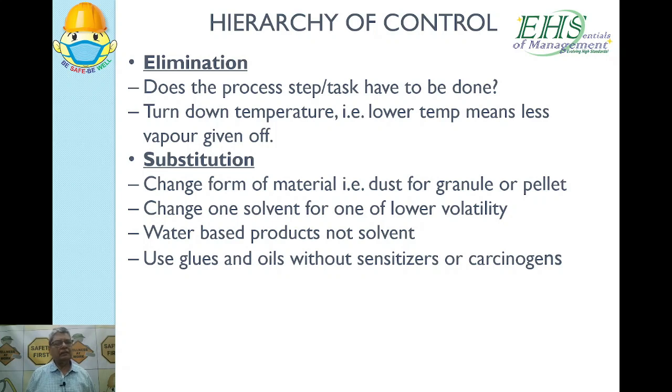Then second is substitution. If elimination is not possible, try to substitute. Change form of material, that is dust for granules or pellet. So in case of your blasting, if you are using granule or pellet, but if it is possible to use the dust, then you can use the dust. So there is a lesser chance of the harm.